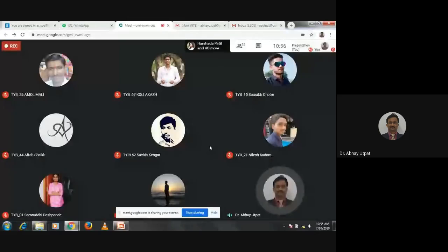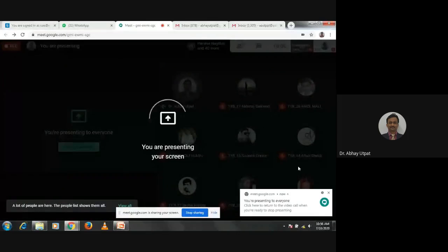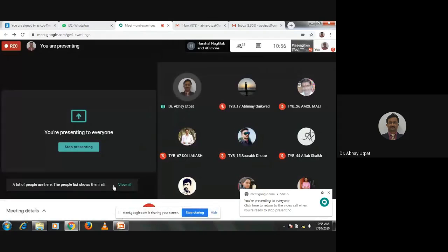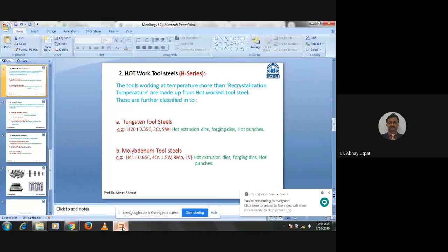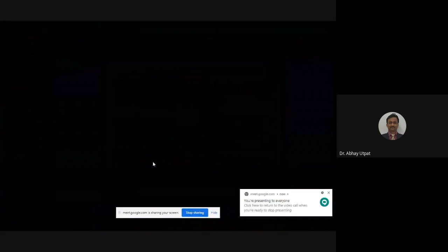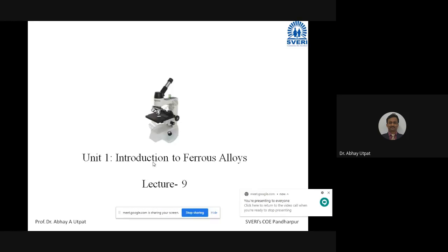The capacity of maintaining the high hardness for tungsten type is more than for molybdenum type. So if you use molybdenum as the main element, molybdenum will reduce the cost. It will fulfill the work, but the cost will be saved. I think it is visible now. Okay.